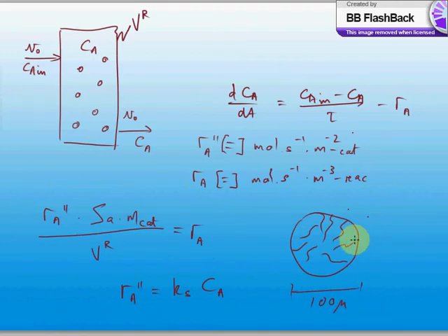But the pores, if we magnify a pore here, let's say there's a pore, right, that we're looking at. So here's one of the pores magnified. The molecules actually diffuse into these pores, and then there are active catalyst centers impregnated on the walls here, and so the reaction is actually happening inside these pores here.